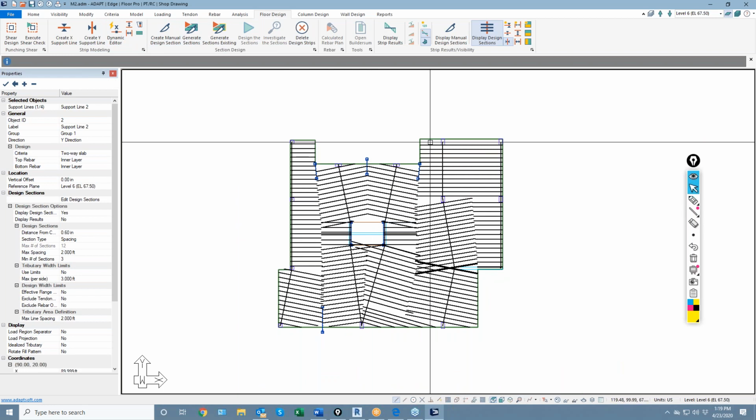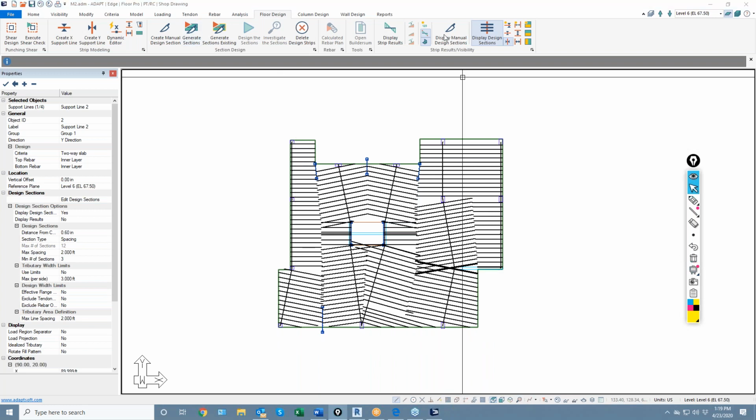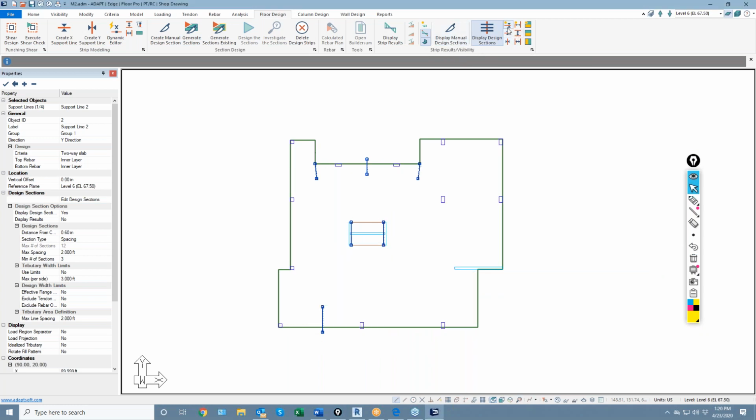Okay, and these are my strips for this direction. Now I could go through and model the X direction strips. Let's do that, and then I'll come back to these and use it to do the tendon modeling. To control the visibility of this, I can use this visibility panel for strips, and I'll just turn off my strips and my splitters that I've added. So both directions are completely unique.